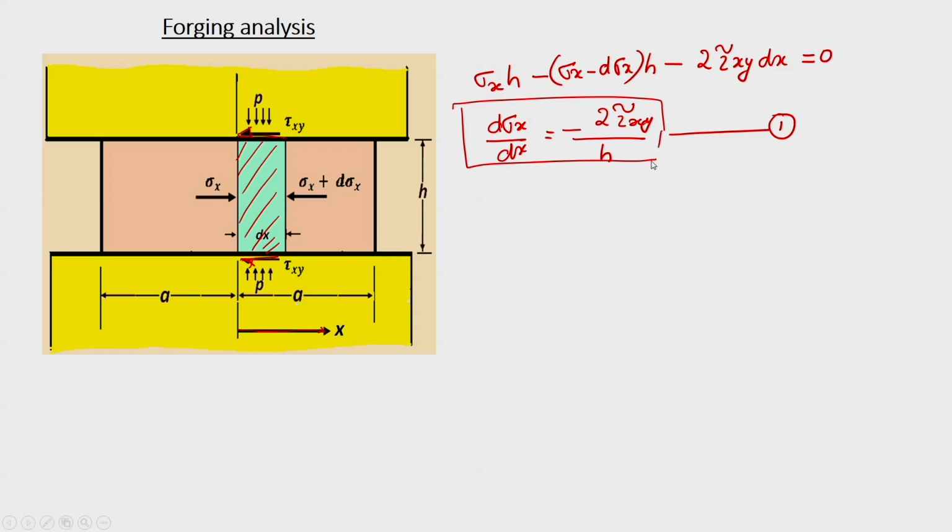If you consider the von Mises criteria for a plane strain condition, which we have discussed earlier at several instances, that is sigma 1 minus sigma 3 is equal to 2 by root 3 sigma 0, where sigma 0 is the uniaxial yield strength of the material. So, that we can write it in this. This is the notation which you always use, sigma 0 dash.